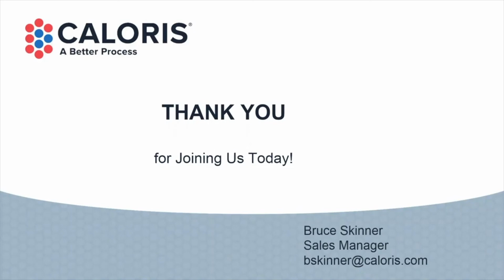Thanks, Bruce. We do have one question that's come in so far. How do you decide the size of the orifice? That is by trial and error. And it is as simple as you try one, you monitor how the system is performing, try another larger or smaller, see how it's changed. And I mean, truly that is the only way to do it. We do try to do theoretical calculations to predict it ahead of time, but we always go to the field with a set and inevitably are switching them out, trying to find that optimum size.